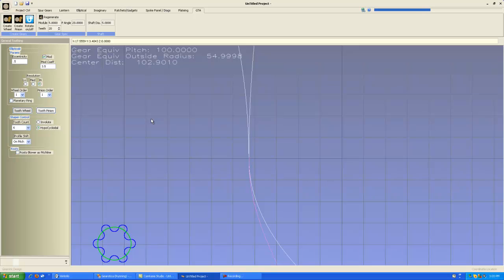And this is why I refer to this page as more of a kitchen. You're going to have to play with shaper parameters, resolutions, and perhaps profile shifting on the shaper in order to create teeth that will do the job that you want to have done.